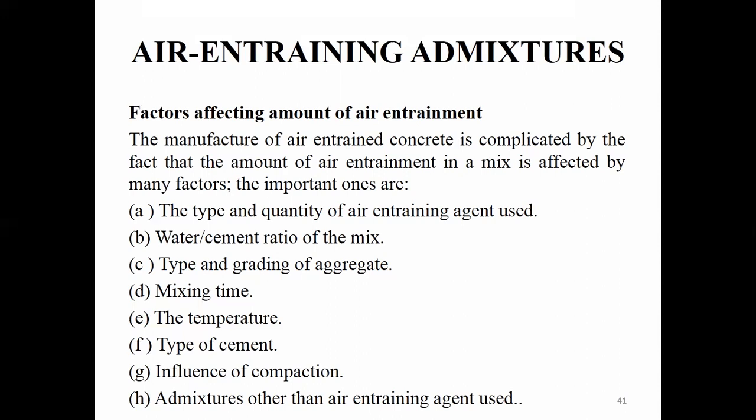Next we are going to discuss compaction. You know very well, if you are compacting the concrete for more time, surely the air bubbles will get reduced. This is just similar to the mixing time. When you keep on mixing the mix for a long time, the air bubbles will get reduced. Similarly, when you are compacting, the air bubbles will also get reduced.